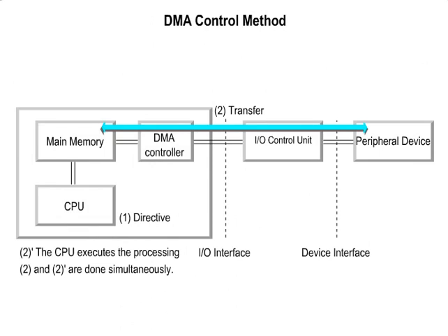2. DMA, Direct Memory Access, control method. In this method, the main memory and the peripheral device directly input or output data without CPU control. Because the I/O is handled by a dedicated DMA controller, high-speed transfer is possible. It is a method that is widely used for PCs, etc.